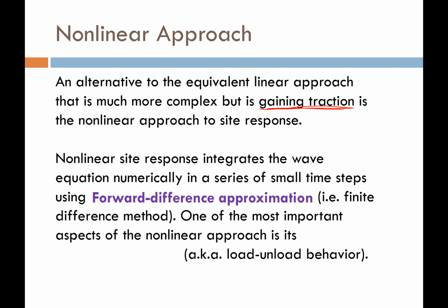The most popular is just this forward difference approximation method. So it's like the finite difference method. And so we're quite literally just time stepping our way through, increment by increment through the time history, layer by layer by layer in our soil profile, and just brute force solving the wave equation.